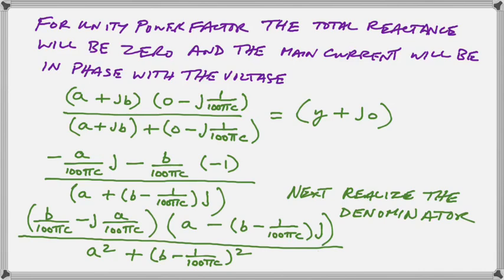Now in this case, the first Z is the equivalent impedance of all our motors, which we just worked out, A plus jB. And the second Z is simply the capacitor, so it has a 0 real part, and the capacitive reactance is obviously 1 over 2 pi Fc, the capacitance. So we have our omega there, 1 over omega C, as the reactance,